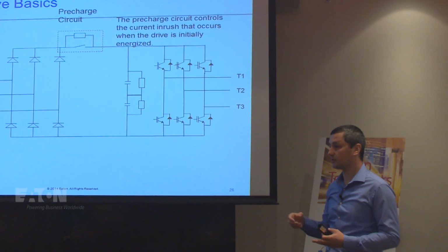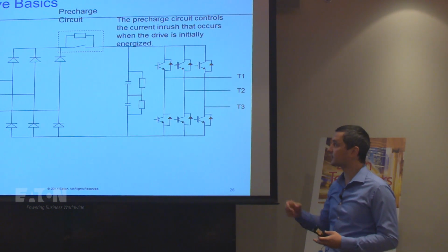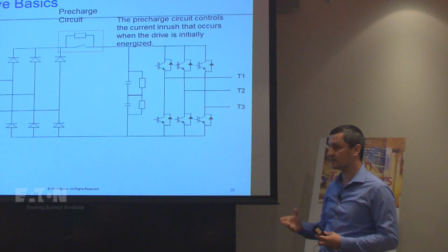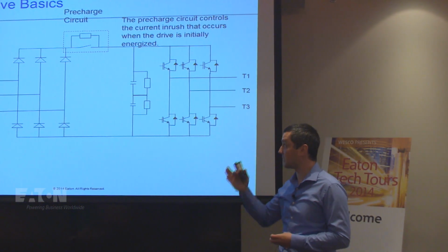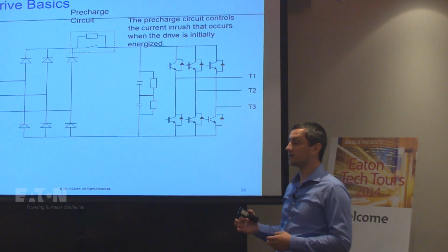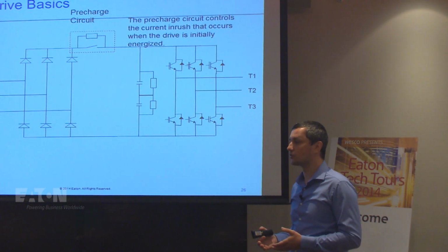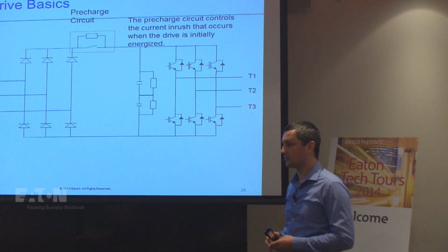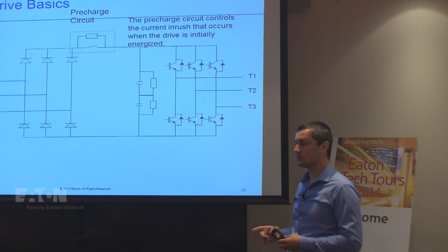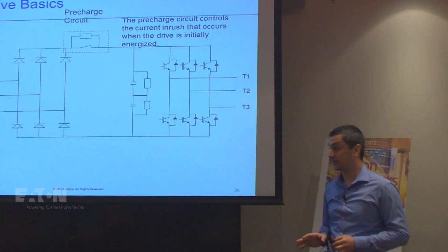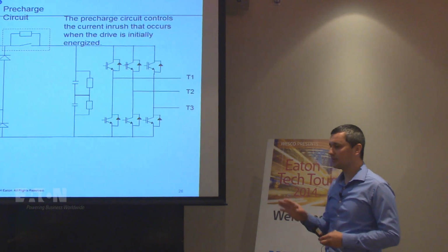Usually with the drives, whenever you're powering up the drive, you'll hear a click, okay? That click is actually that contactor closing and bypassing the resistor, and that's when you will get your ready signal for the drive, okay? Until that is closed, the drive will not be able to operate, okay? Very important.